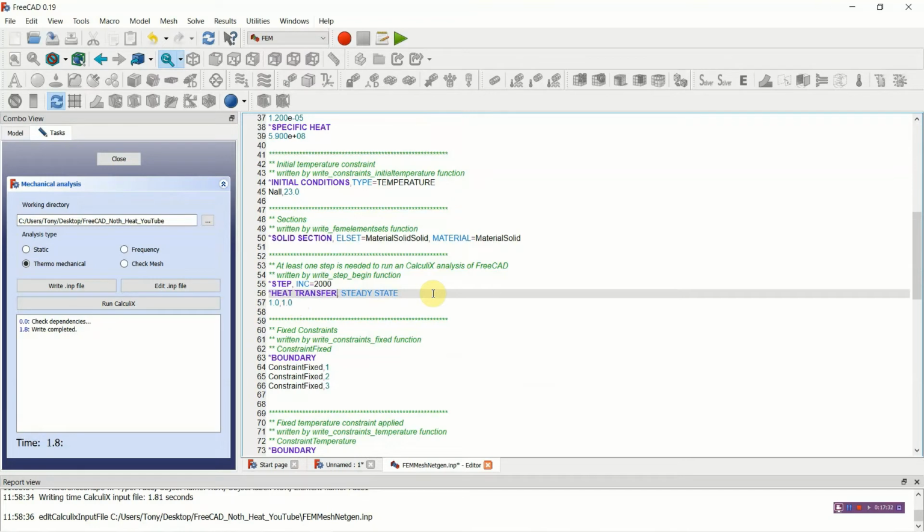It will compute the characteristic matrices for the elements around the outside and around the hole for the convection. And you'll have a right-hand side containing the vector of convection surface heat transfers. It will invert the total characteristic matrix and compute the temperatures.